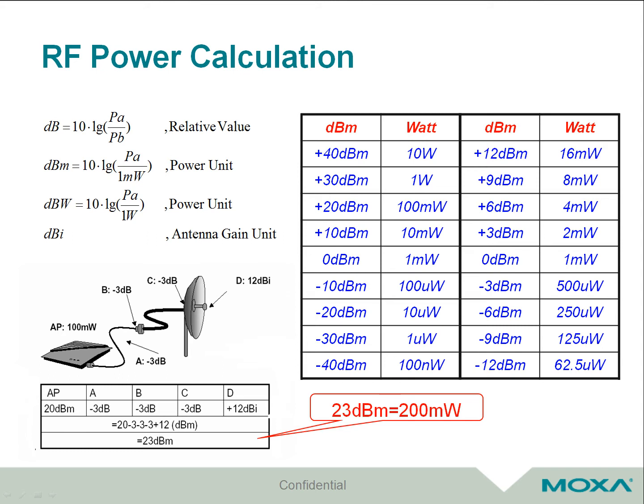Depending on base power value, we can have several commonly used decibel units. If you take 1 milliwatt as a base power, it would be dBm, or decibel milliwatt. If base power is watt, then the unit is called dBW, or decibel watt. Antenna gain is measured in dBi, which stands for isotropic decibels. This relates to isotropic radiator concept that I mentioned earlier.